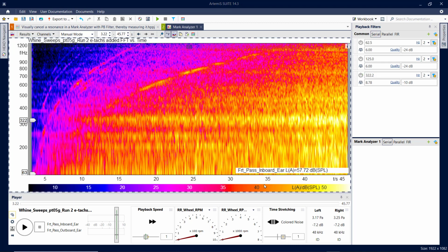I like, with a playback filters tool window, before I do the next thing, when I finish using it for something, to set the filters back to their defaults, which are 62.5, 125, and 250 hertz, with a 6th order slope and a certain Q, an attenuation of 24 dB. So you can individually for a filter save and recall, and you can set and save and recall a group of them. The default has 3 filters.